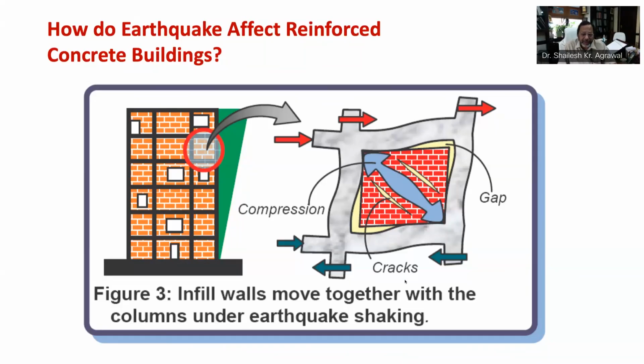However, remember, an infill wall unduly tall or long in comparison to its thickness may fall out of plane, that means in its thin direction. This out of plane failure can sometimes be life-threatening and should always be avoided. Also, infill irregularity in the building causes other ill effects such as torsion, stiffness irregularity, short column effects, etc.